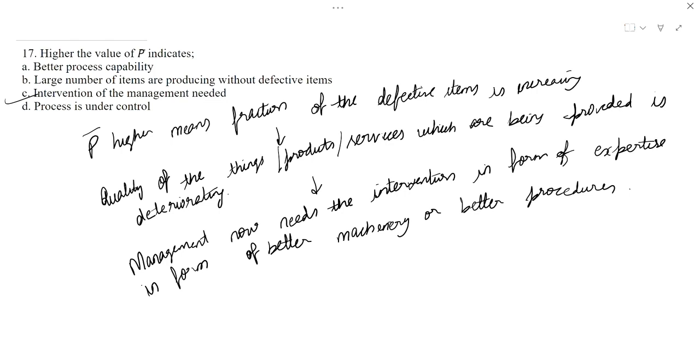On the other hand, if the process gives P values randomly here and there, with no non-random pattern but a random pattern, that shows the process is under control. But if the points start falling beyond the control limits, it suggests that the same process which was doing well, producing fewer non-conforming items, has started to go wrong.